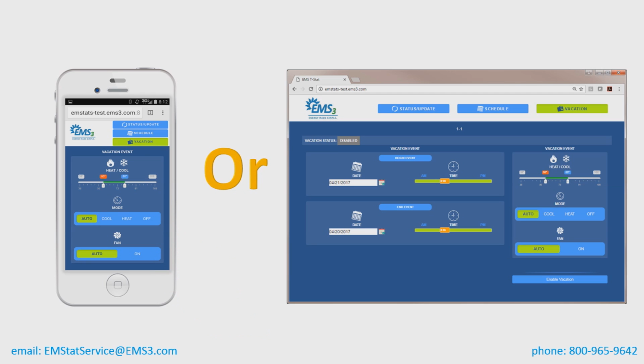After mode and fan, set the temperature range you want to maintain while you are away. The lower you set your heat setting and the higher you set your cooling setting, the more money you will save. In other words, a wide range saves you more money than a tight range.